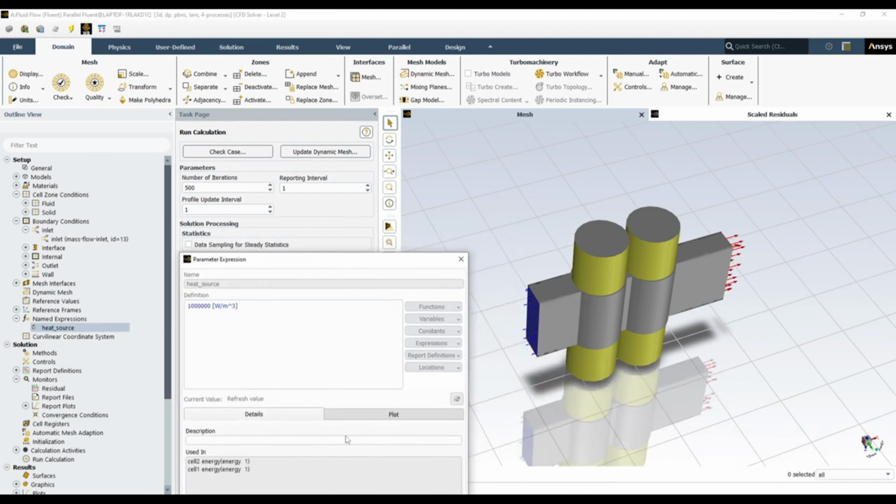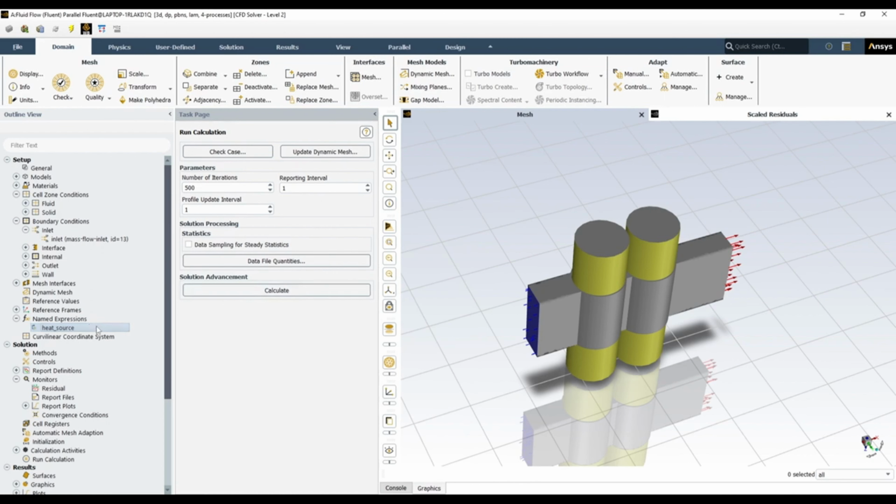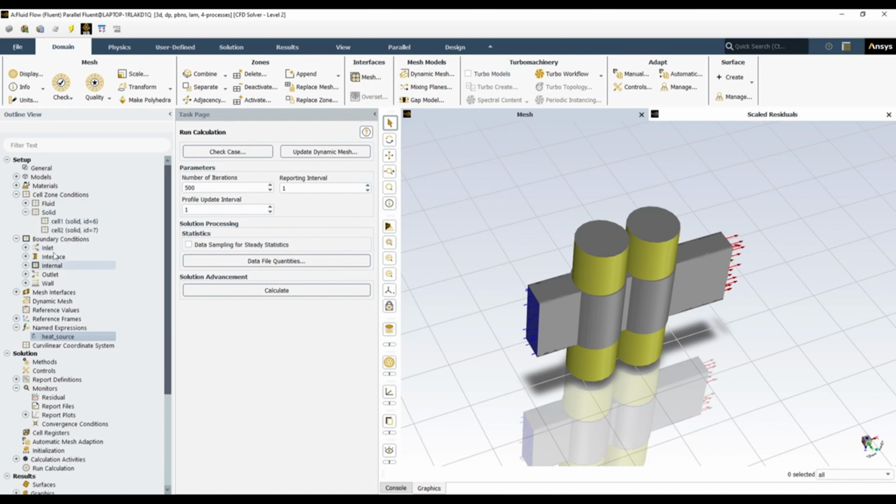So heat is this many watts per cubic meter, because we have to provide heat per cubic meter. It is approximately 2 or 3 watts per battery cell. I have to check, but you can get it by multiplying this number with its volume, and you will get watts. How do you do that? Maybe you are already aware.